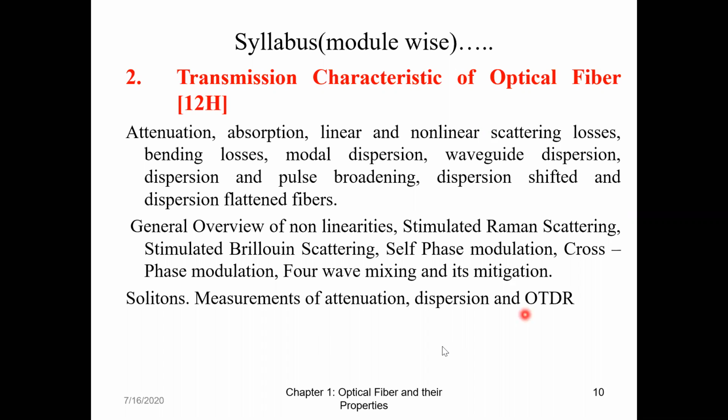So we have a device called OTDR, that is optical time domain reflectometer. This is a costly device used by whoever is dealing with fiber optics. I just send a light through a laser in the fiber. Now what happens is, suppose there is a fiber cut somewhere. I'll show you the detailed diagram, but today, in this introductory lecture, I'm just telling you.